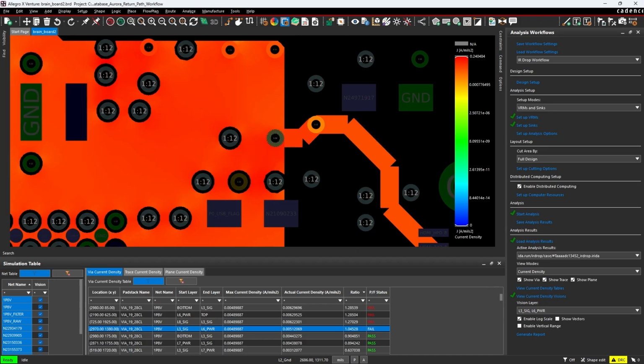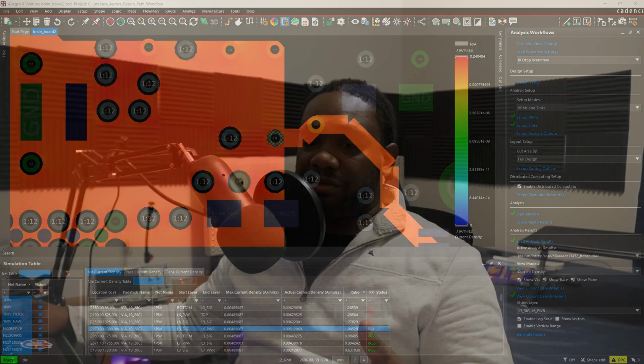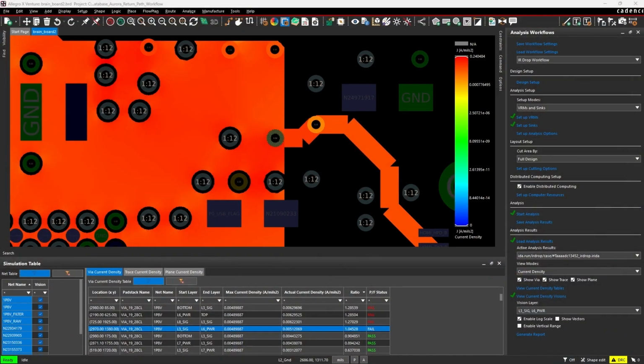So what that means is just because you place more vias doesn't necessarily mean that your current density is going to be suitable for that area. What that ends up looking like is your board goes out in the field, it's used for say 6 months, 12 months, and then people report that there are some heating issues, some problems with the temperature, and then your thermal cycling starts to happen more frequently than you would expect, and then you have to do a quick recall and test things out. Okay, so that's why this is very useful. It saves you a lot of trouble in the future.